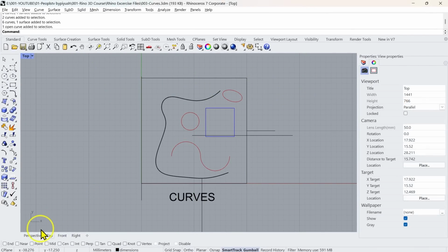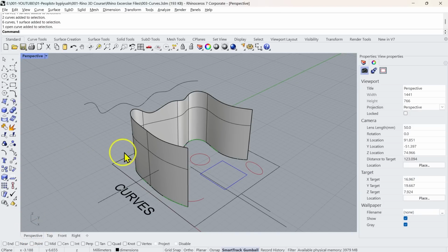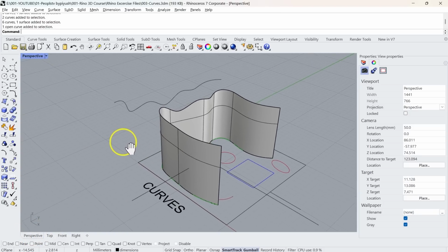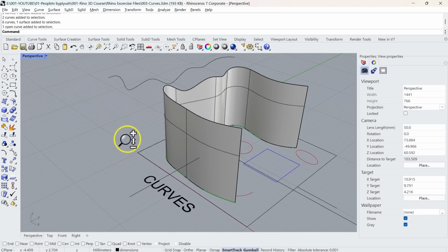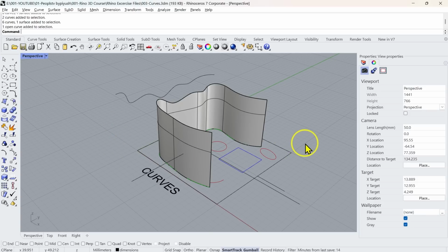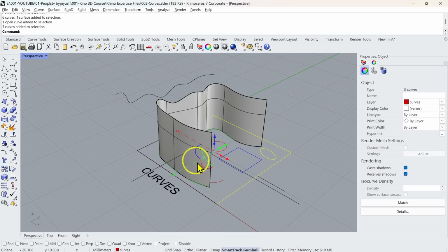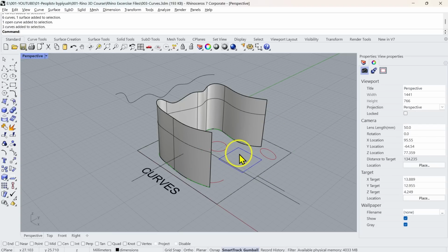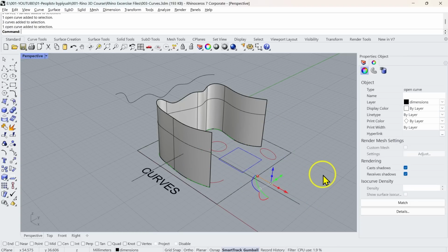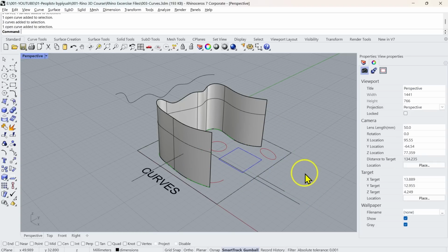Now, let's go to the perspective viewport and understand the navigation there. The panning, zooming, and selection happen the same way as we did earlier. But to rotate and see around your model, hold your right mouse click and drag your mouse to left or right to activate orbiting.